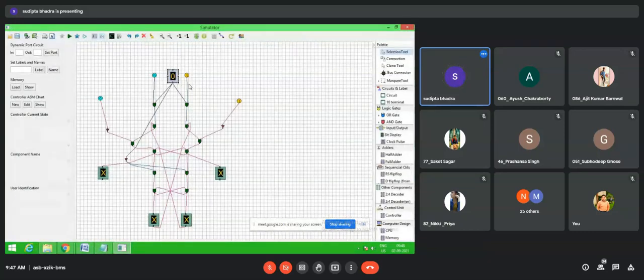So here case analysis means the particular case where H is triggered or not. Okay, so you don't need to concern about this log part. Here you need to concern that whenever there is X, you have to do this case analysis, means the selection should be here, and then gate by gate simulation, and then you start the clock. You do the gate by gate simulation.